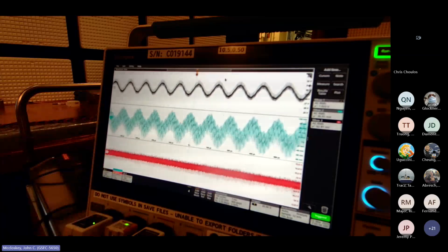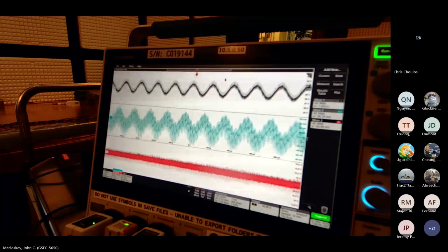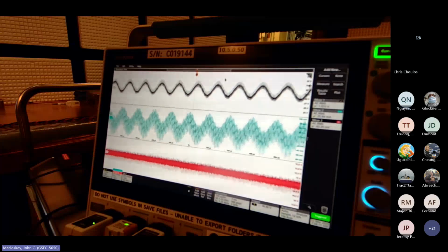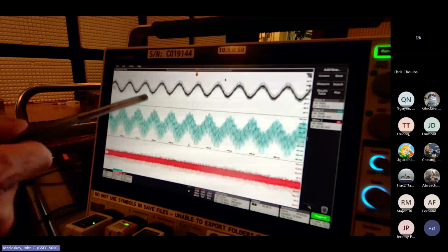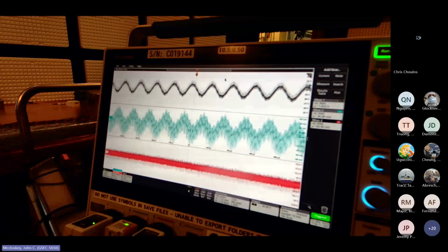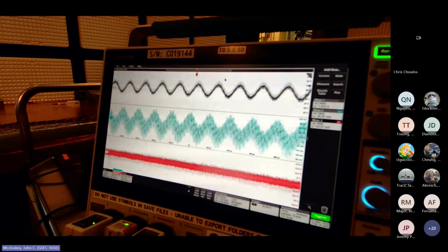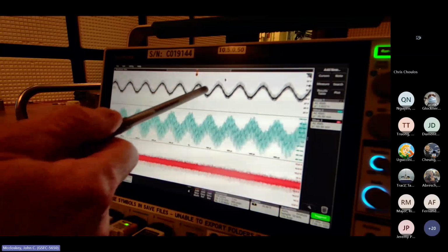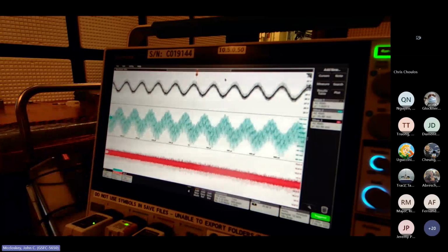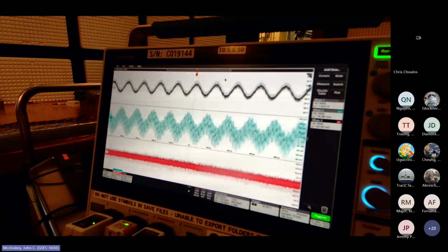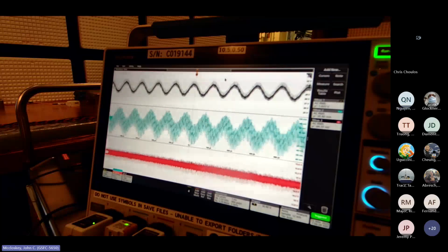So one of the points that I wanted to make here is that when you monitor the current into the EUT along with the voltage, you can get a measurement of the input impedance. And that's exactly how you do it. You measure the voltage and the current. And when you have enough resolution on the phase, you can get magnitude and phase. Now, with this noisy input, it's going to be pretty hard. Right, you got all this junk riding on top of the injected signal. That would be kind of difficult, most likely, to get a really effective measurement of input impedance.